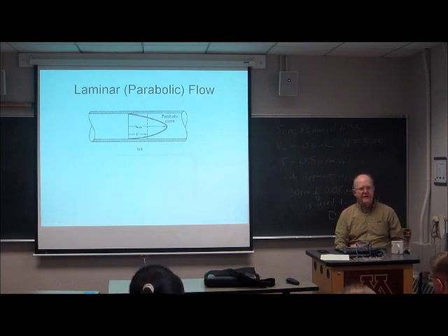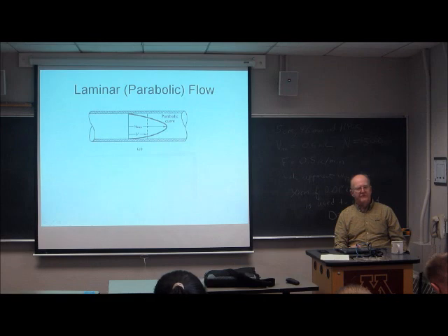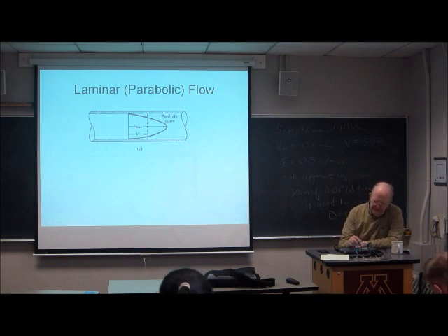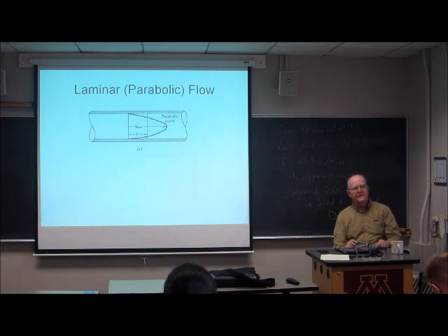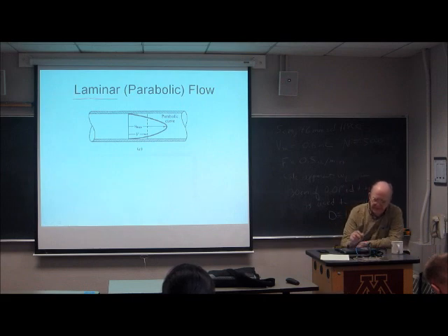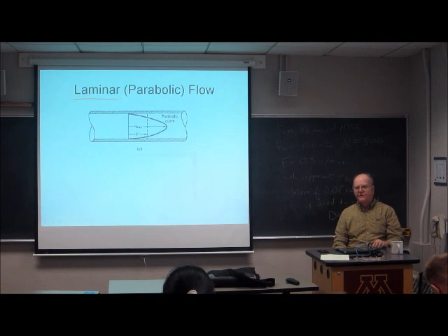So that's supposed to be a diagram of the velocity of the molecules as the distance from the wall of the tube, and it forms a parabola. This is under the condition, the laminar flow condition, which we assume for the Navier-Stokes equation to be solved.